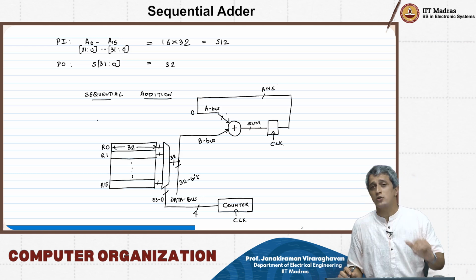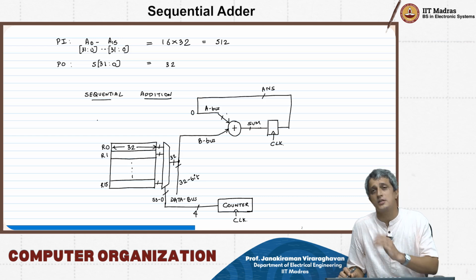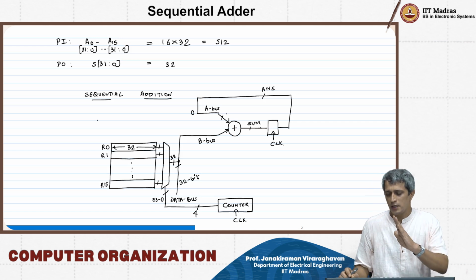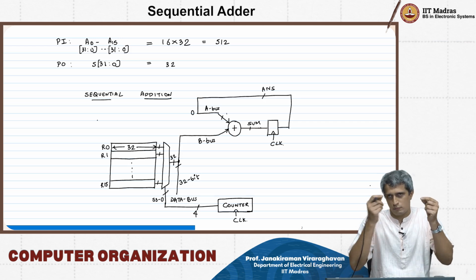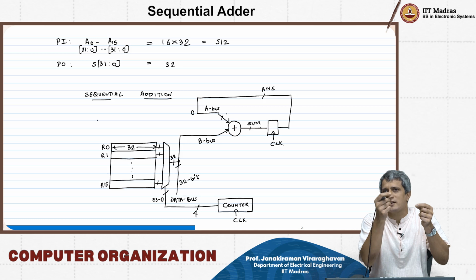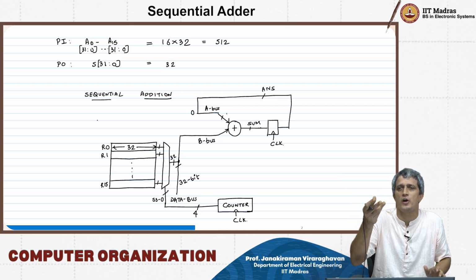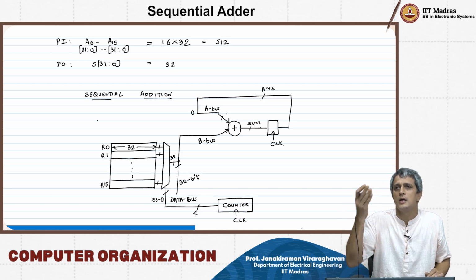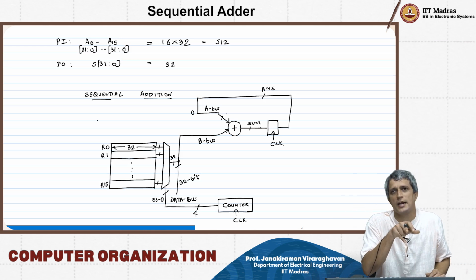Now there is only one problem here: initially, what is the sum in this register? We don't know, and therefore just feeding this back blindly is not going to work. We need to do something interesting, where when you are trying to add register 0 for the first time, this sum and answer should actually be 0 that goes into the adder.